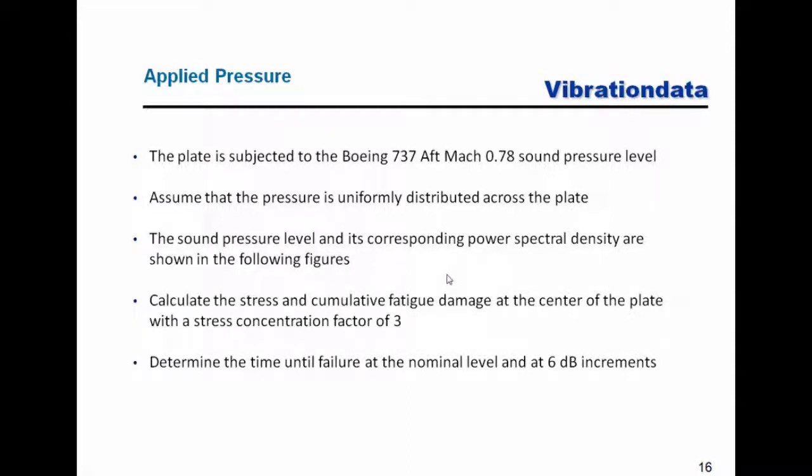And let's see. So we're going to take a look at the corresponding pressure spectral density. This will be a pressure power spectral density. We're also going to assume that at the center of the plate we have a stress concentration factor of 3. So, who knows, maybe there's a hole with a bolt in it or something, but one way or another, for some reason, there is a stress concentration factor of 3 at the center of the plate. So that's some conservatism there.